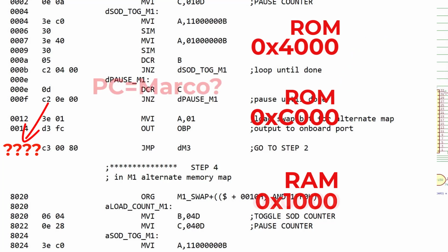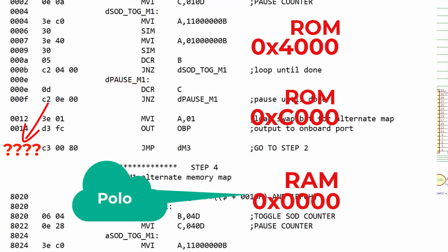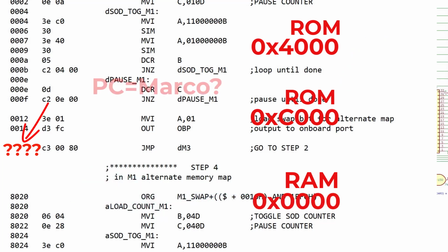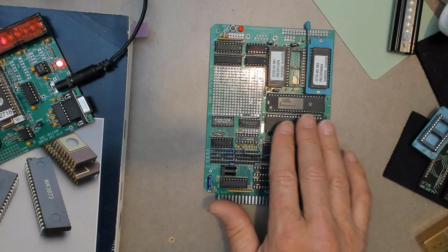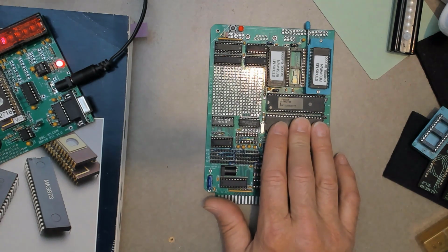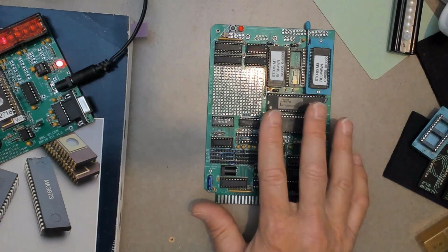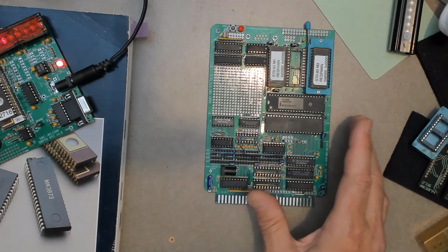And that next memory address may now be in a different device, or it may be nothing but a hole in the memory. That memory may not actually exist anymore. And so that processor, when it fetches from its existing program counter, it may get junk, it may get nothing, but if we plan it right, it will just get the next instruction and it can continue the program.